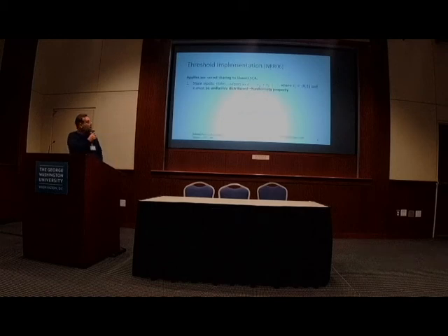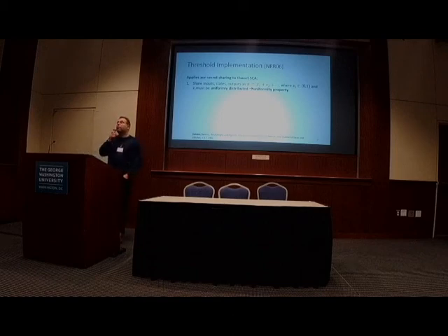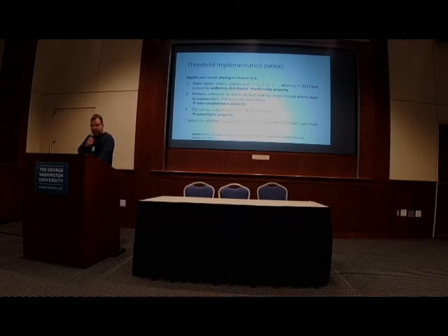All right, so another standard technique that's very effective and has become quite popular in the last 6-7 years is threshold implementations, and they're very effective, especially in lightweight cryptography. Basically, you apply the secret sharing idea on the circuit. You split apart the data, applying the secret sharing idea on the computation path, and then you have to change linear and nonlinear computation blocks to reflect the shared computation.